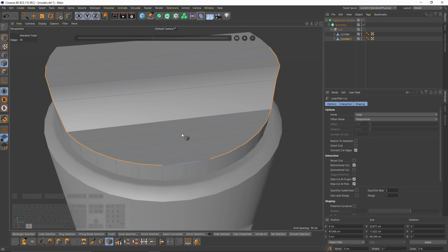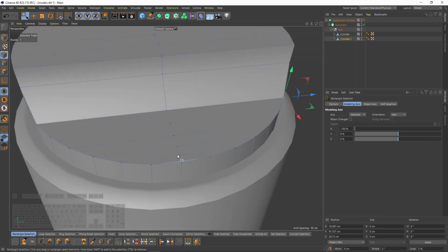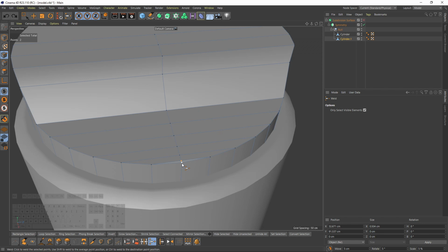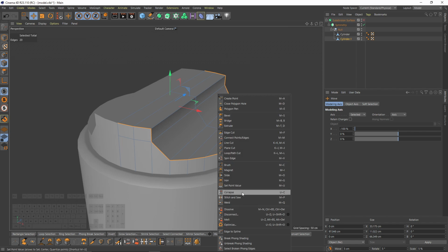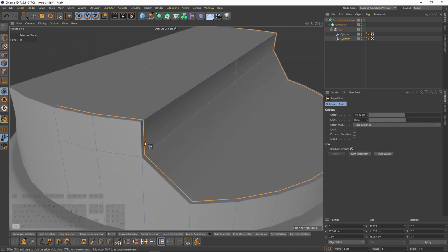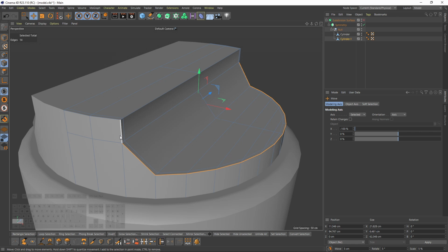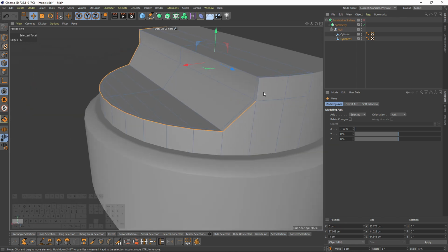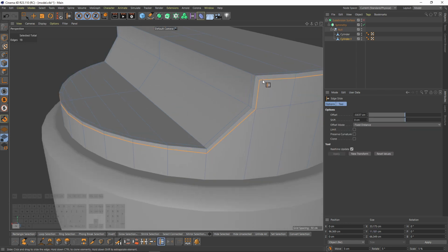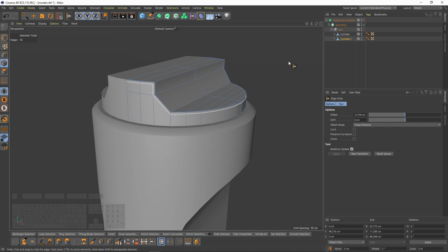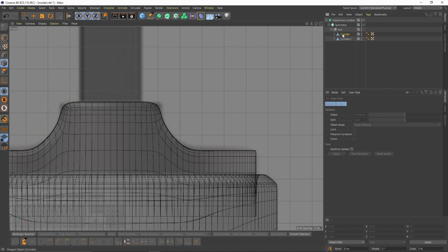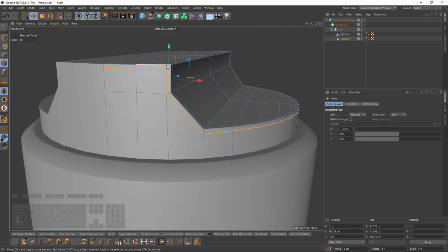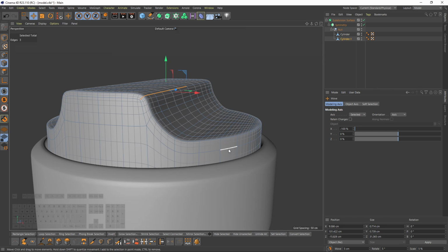And same thing, a loop cut right in the middle, then connect these points. This time I will make the supporting edges with the slide tool. Select slide, press Ctrl and slide inside. Then select these edges one more time. But this time I will slide them like that. Let's press Q. Perfect, except the part that edge shouldn't be that soft.